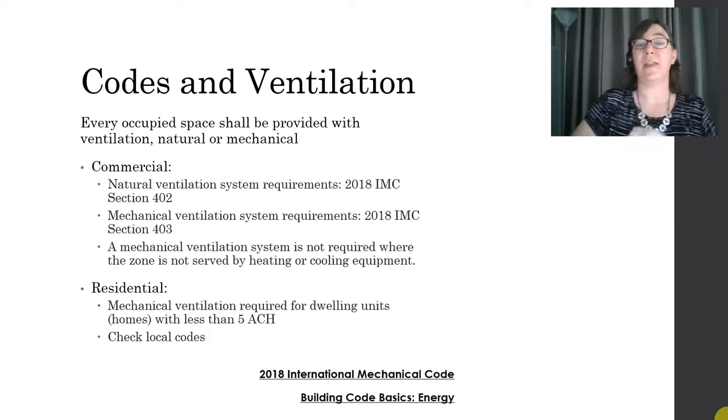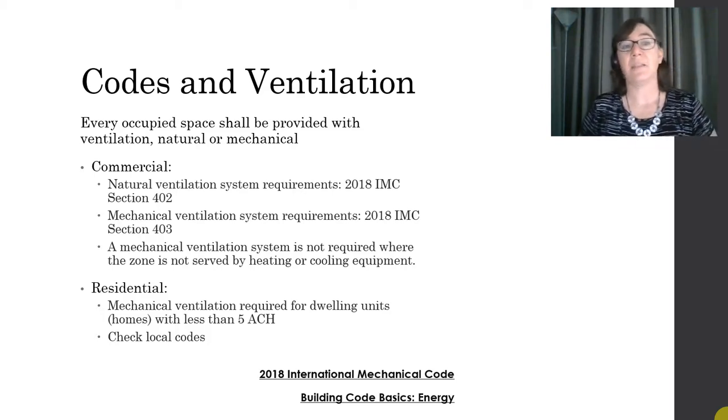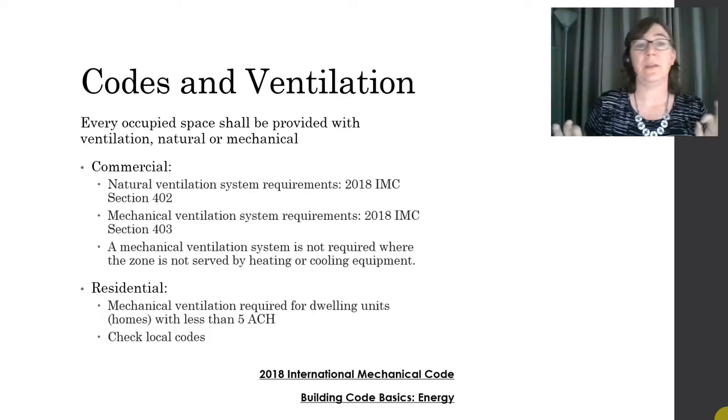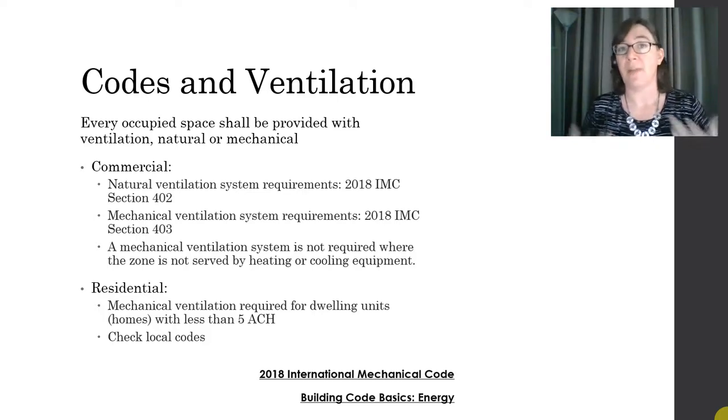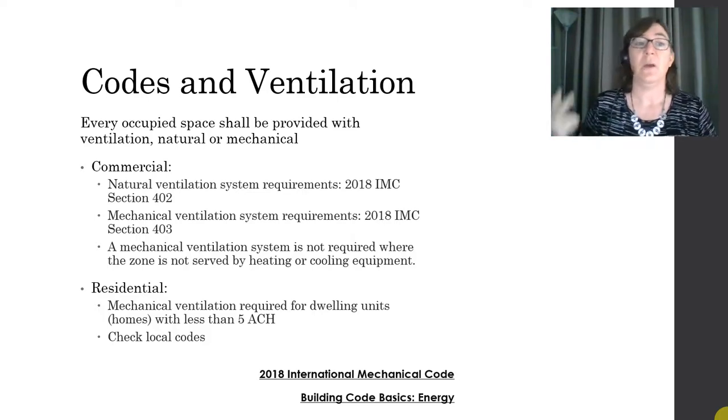You'll find the natural ventilation system requirements in section 402 of the IMC and the mechanical ventilation system requirements in section 403. Also, just note it's not required to provide mechanical ventilation when you're not providing heating or cooling.